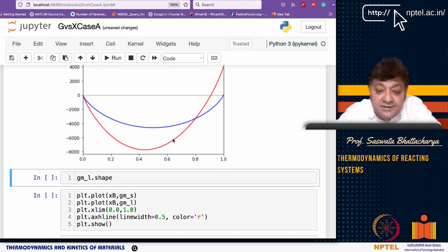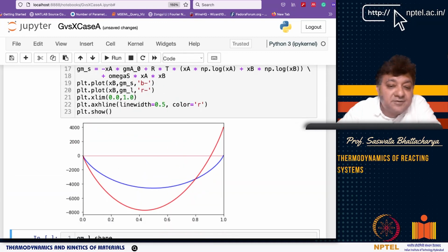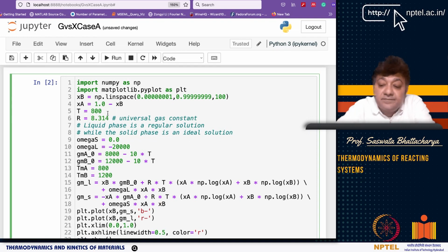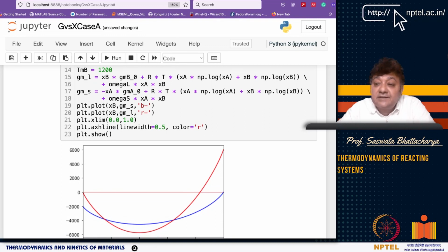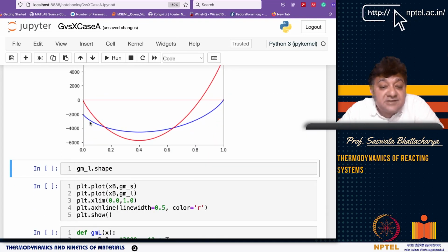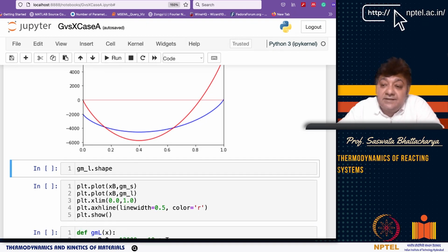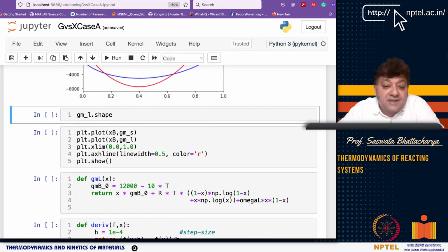But if you see here, you have again a coexistence. However, the coexistence curve is such that you are now slightly less B rich. I will not solve the chemical equilibrium conditions numerically, but I will draw common tangents here for these different temperatures. Again, I can use some temperature like 600. Now you can see that there is coexistence on both sides, right? On the A-rich end, you have this common tangent possible, and there is another common tangent possible. So I want to plot these tangents and see.